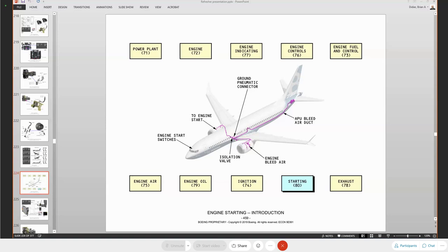Okay. The other thing you have to be careful of with manual override is, remember, the valve or the port that you're going to be using to wrench the valve open or close is in front of the red line. So you're going to have to make sure that your safety harness is on and other such things.